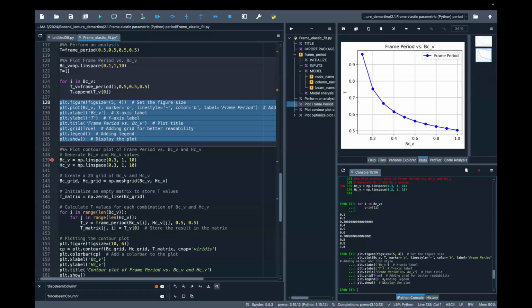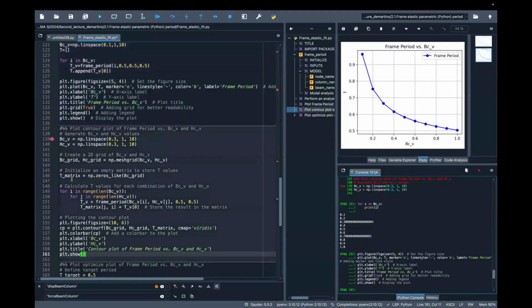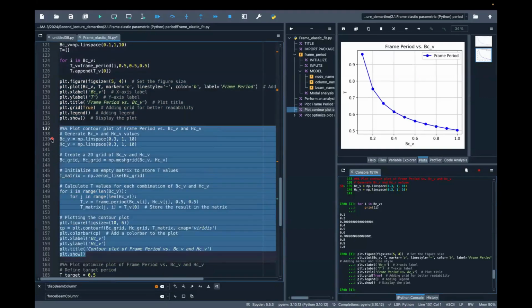Obviously, that's a slight extension of the approach, like my colleague when he was doing the Monte Carlo analysis by hand. So if you have 2 variables, I think you can extend the concept as you can see here, in the part I highlighted from line 137 until 169. Here, it's the simple extension of this concept in 2 variables. So we want to investigate the variability of the period by changing the base and height of the column. You can see it is simply an extension.